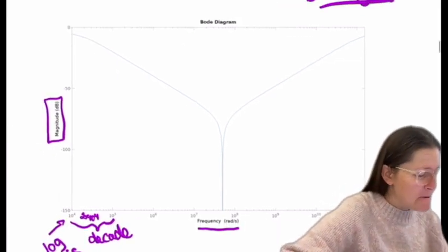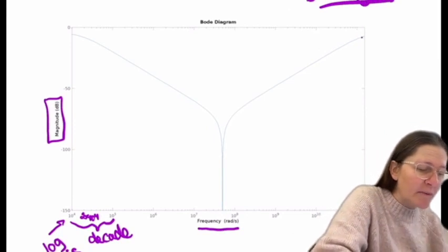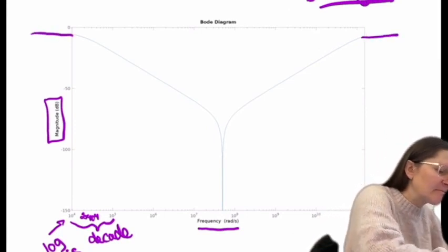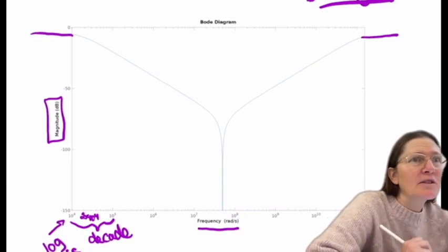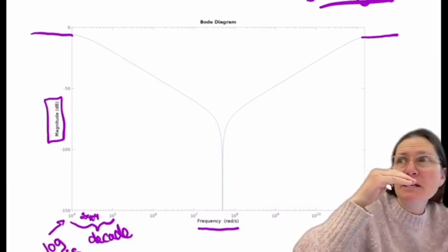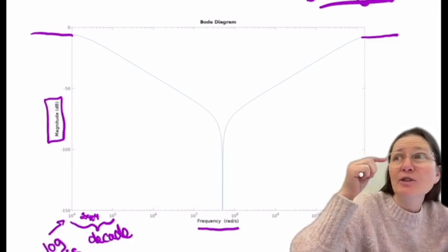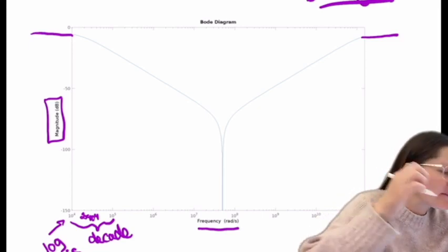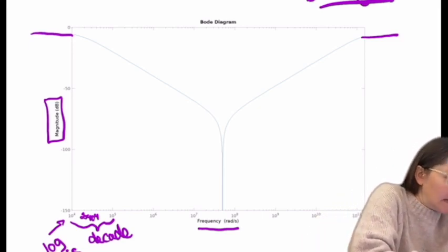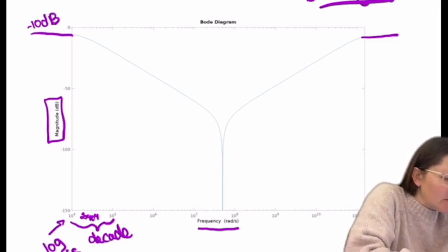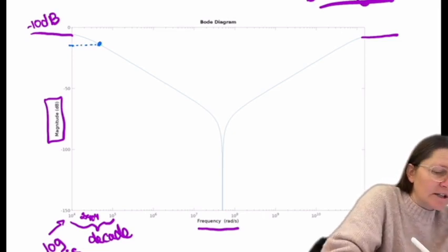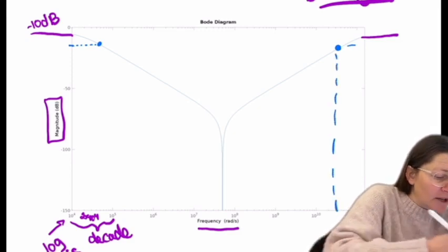It looks upside down. So you have to look at what the main flat region magnitude would be. And then remember the corner frequencies are 3 dB less than that. Remember you're looking at the averages or the RMS value. So whatever that value is, if this is, making a guess, minus 10 dB, your corner frequency is actually going to be 3 dB less than that. So it would be around here, and around here. So this would actually be your whole region.